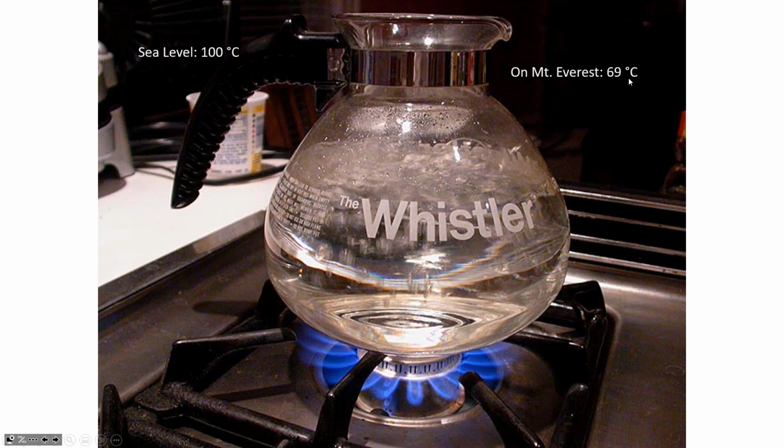What it relates to is that when you've got water and it's open to the atmosphere, water molecules are trying to go into the vapor phase to some extent. There's something called a vapor pressure, P sub V, which is related to the kinetic energy of the water molecules that are in the water, and whether they have enough energy. A certain fraction of the particles will have enough energy to go from a liquid to a gas. And the atmosphere is pushing back at any given time.